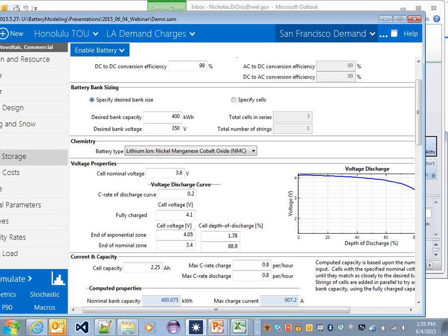It might also be slightly affected by the physical build of the battery. One manufacturer's battery with one chemistry might have a slightly different voltage curve than another manufacturer's battery of the same chemistry, but those differences are likely to be quite small compared to differences between different chemistries. So I'd say the chemistry is the primary driver of the voltage.